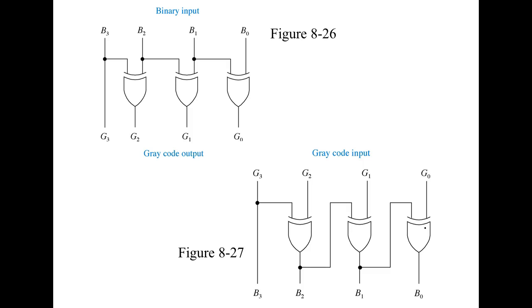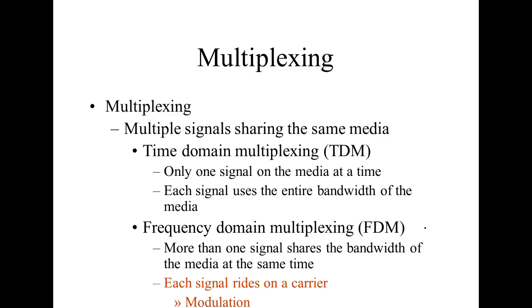Well, all your broadcast radio stations are flying through the air, right? All your broadcast TV stations are flying through the air. How many cables do you have running in the back of your TV or your box? One. How many channels do you have riding on that thing? A bunch. Plus your network, right? So usually your internet comes through that cable too, right? So multiplexing is when we let multiple signals share the same medium. That makes sense. So multiplexing, multiple signals share the same media.